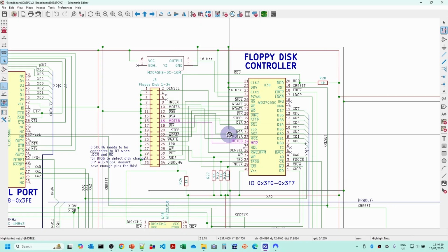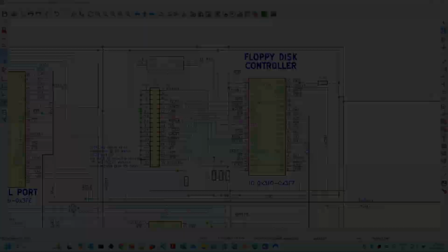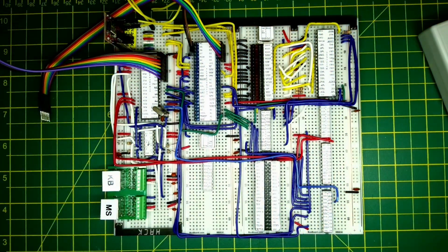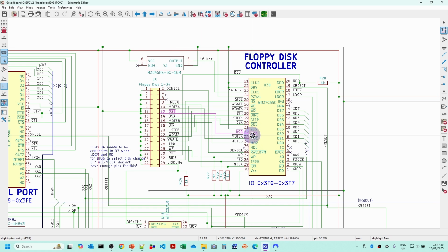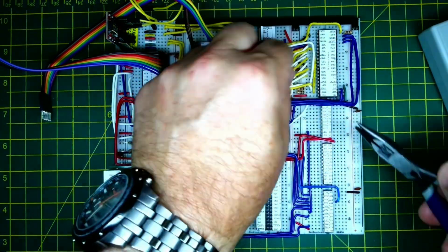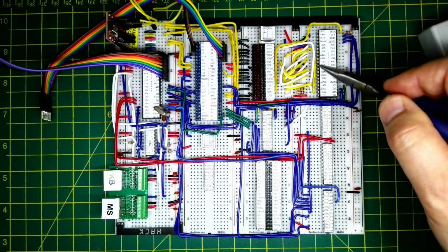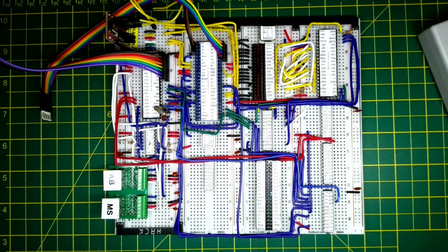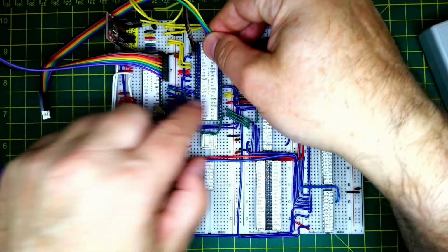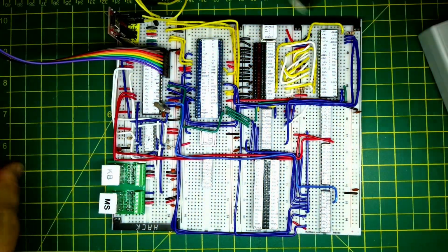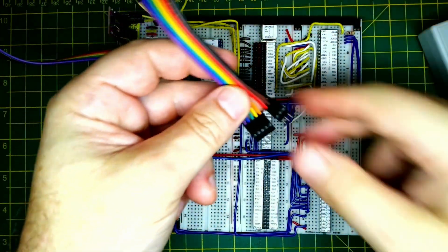And then the motor B and drive select A. So that controls the sort of drive 1 motor and the drive 0 enable, and then the disk select B and motor A. Then we'll just check that we've done all the pins we needed to do, other than the data lines there. I'm just going to swap out this cable, which is a 5 and a 3, but it's just quite long. I'm going to make up this cable, which is a bit shorter.